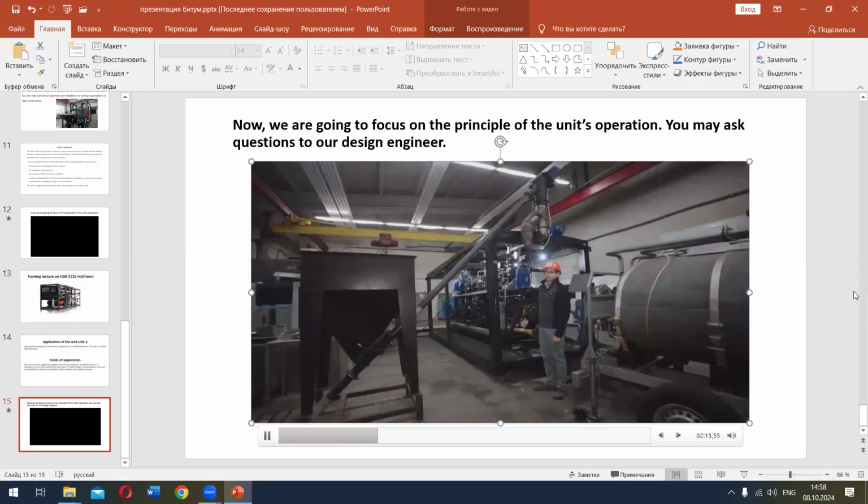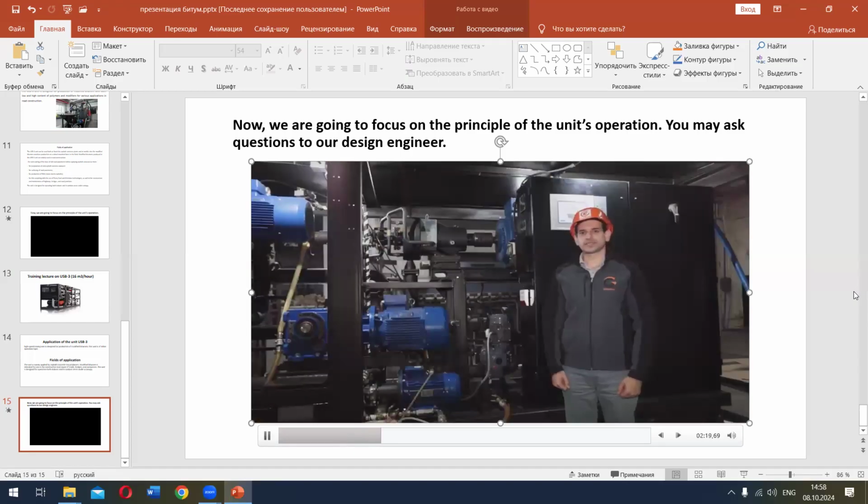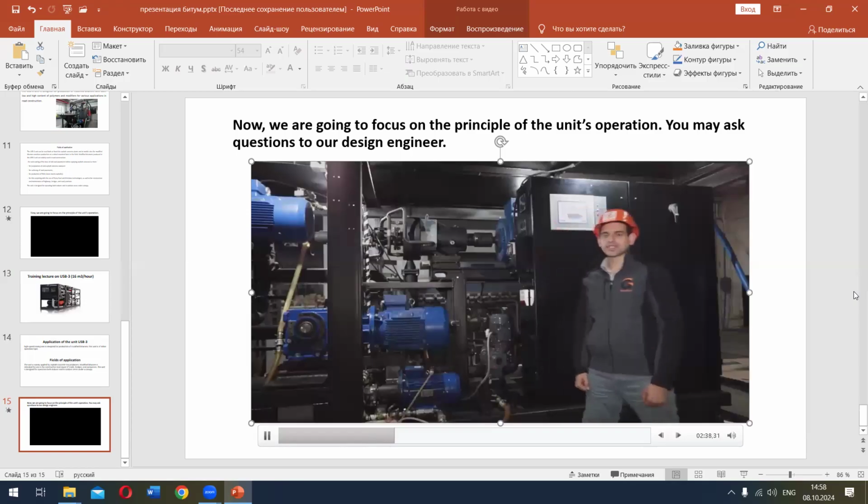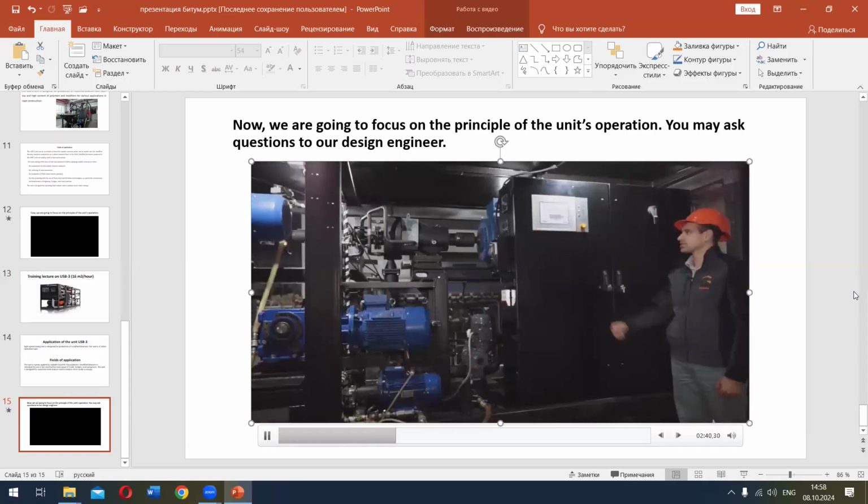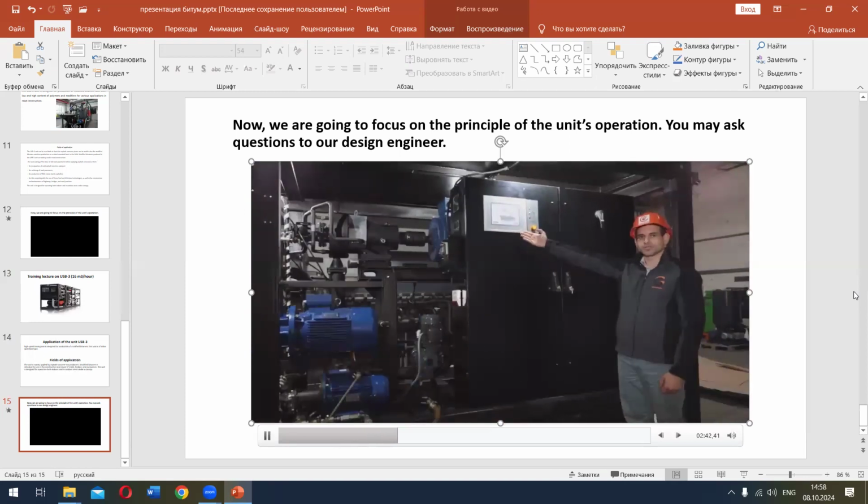This pump group is equipped with a feed adjustment valve which allows the operator to switch. Calibration curve data must be entered correctly. It is worth noting that calibration of components takes not longer than one shift. Recalibration of components may be required only in one case: if the components in use are to be replaced.